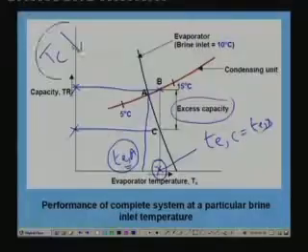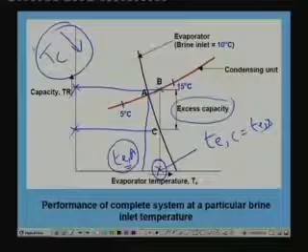When the condenser has excess capacity, since the size of the condenser is fixed, it can condense more mass flow rate, or what it can do is, for the given mass flow rate, the condensation can take place at lower condenser temperatures. That means your condenser temperature Tc will be reduced. Once Tc reduces, evaporator temperature also reduces. Once evaporator temperature reduces, the balance point will shift now from the unsteady value of TC to the steady value of TB.